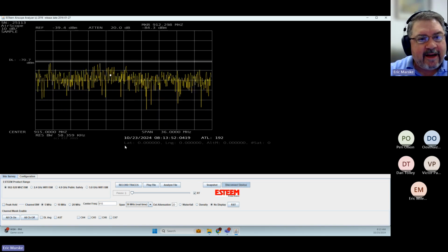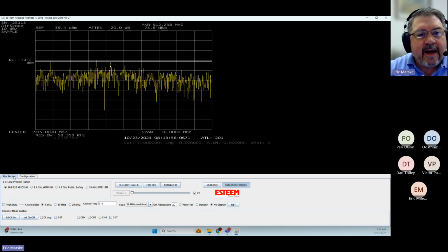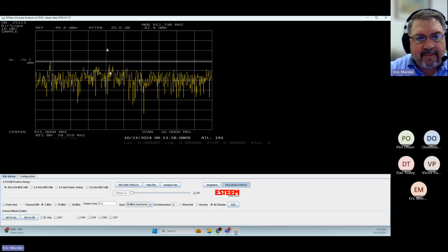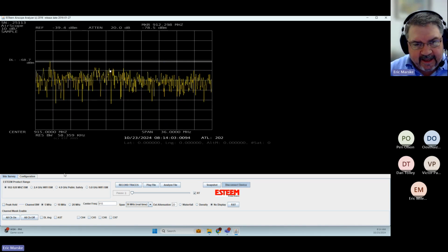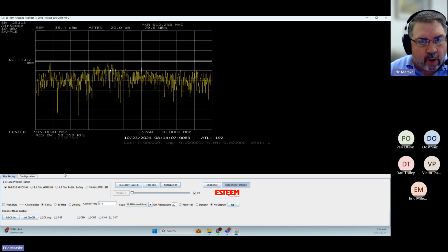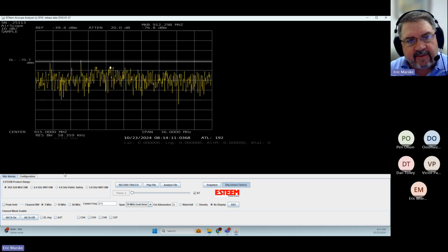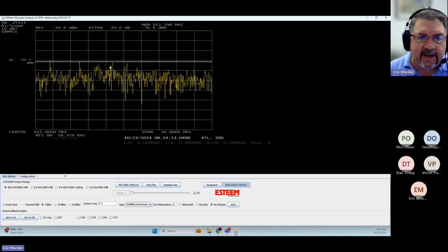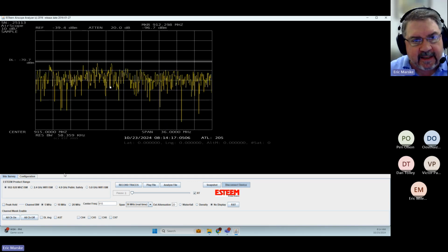And what I've got is I actually have in our channel here, you might be able to see it every once in a while, it pops up and marks it here. In most cases, in most spectrum analyzers, especially when you're dealing with single channels, you use what's called a peak hold. Now, what a peak hold does is it basically looks at all of these line elements that are going across here and will display and mark the highest level that it picks up.